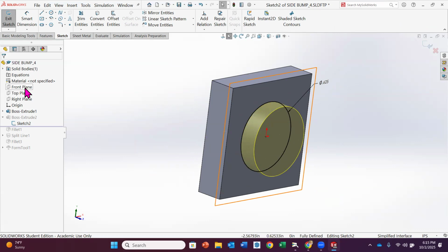So now what I have here is that plane is identifying my stop surface. You want to do that because when you put this in place, it's going to recognize that stop surface and it's going to put it up against whatever side you want it to be on. If that surface is on the back side of this, it's not going to create the form. Does that make sense to everybody? So just be aware of that. And like I said, they kind of leave that out of the tutorial. Believe me, I experienced it and I'm like, why isn't this working? And I realized, oh, you've got to have that stop surface as your plane. Okay. All right. So I just want to kind of save you from having to figure that out. All right.